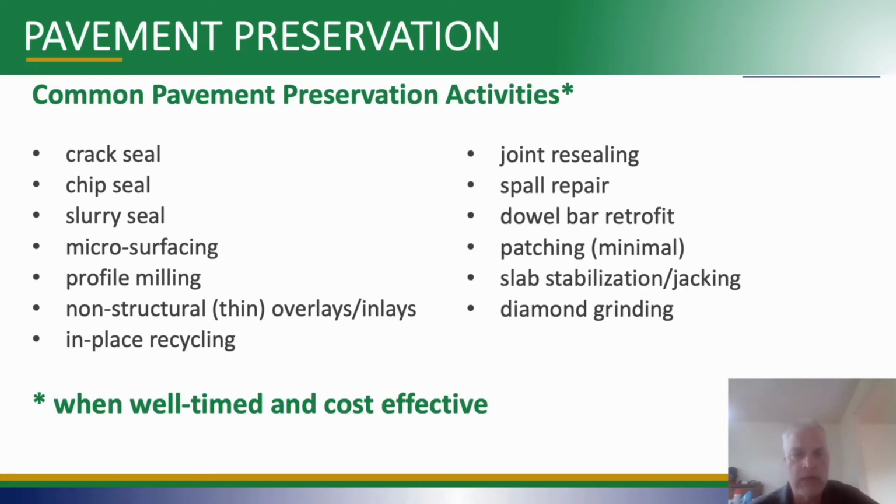So here's some common types of work that are considered preservation when they're done at the right time. All of these activities, if you look at them, they can be considered maintenance, they could be considered preservation, they could be considered repair, and it all depends on when you're doing it. If you're trying to do it to a good pavement or even a fair pavement, it's preservation because it will maintain that level of condition.